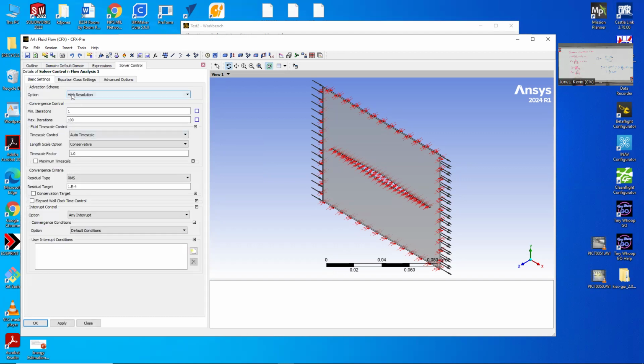We don't have to do a lot here. We're going to use the mesh refinement. That's this thing up here. The trick is, what it does is we'll pick a variable that has some gradient we want to cluster points around. So density turns out to work great. The way it does it is it sort of subdivides cells, like cuts them in half or quarters. And once it adds new cells, it's very reluctant to give them up if they turned out to be in the wrong space. So I don't want to do any refinement until I at least have a pretty good stab at where the sharp gradients are going to be.